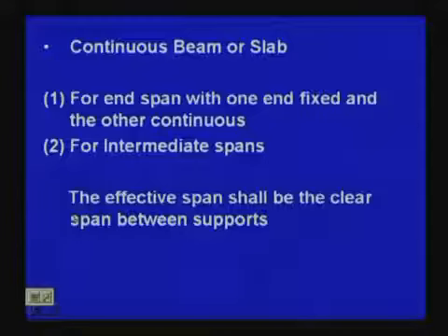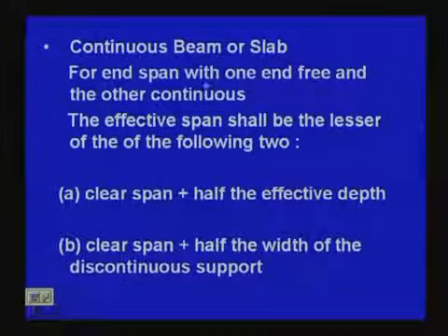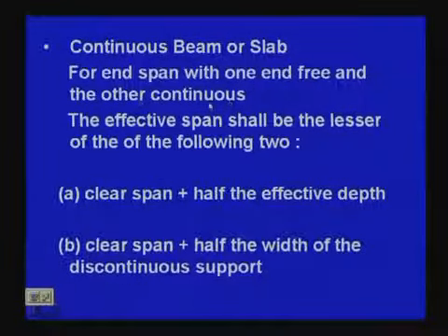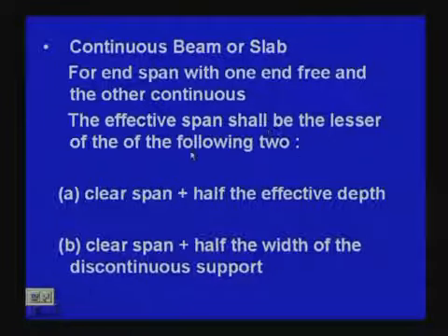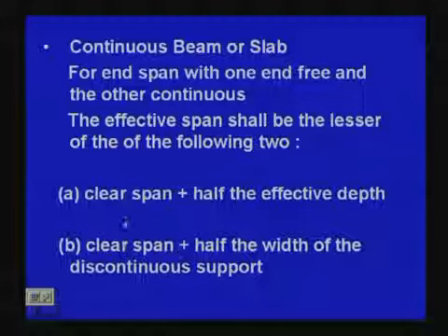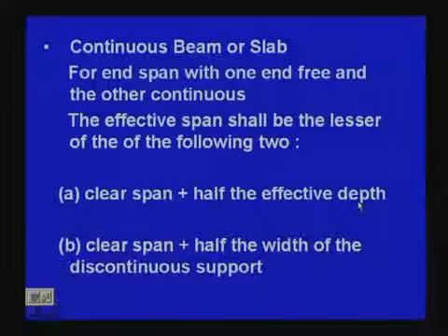What about the other case? For end span with one end free and the other continuous, the effective span shall be the lesser of the following two: clear span plus half the effective depth. Please note, clear span plus half the width of the discontinuous support.